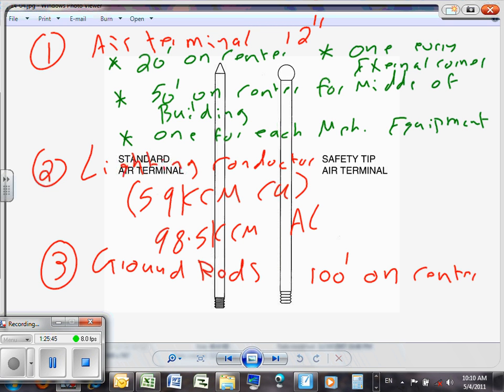So for the ground rod, I don't think we have a family for the ground rod, at least if I remember right. We're going to have a little symbol, guys, that shows a ground rod, similar to what we have done. It looks something like this. That's my ground rod right next to the building, and you drop a wire, annotate a wire in Revit, and tie to it. The size of the ground rod we're using is 10 feet by half an inch minimum, per the recommendation here.